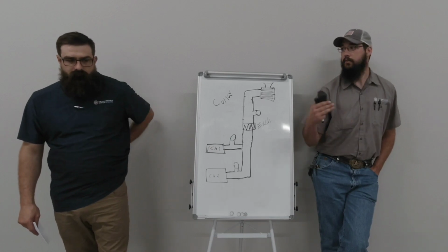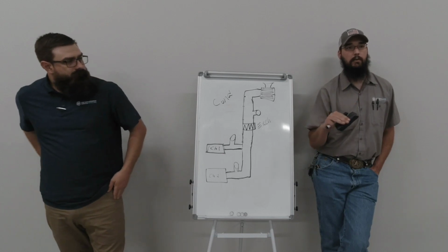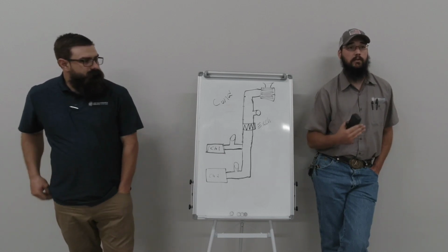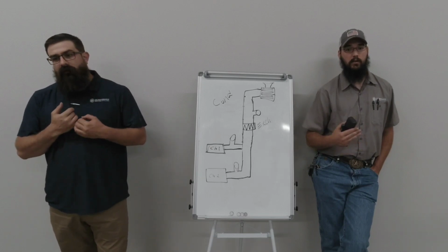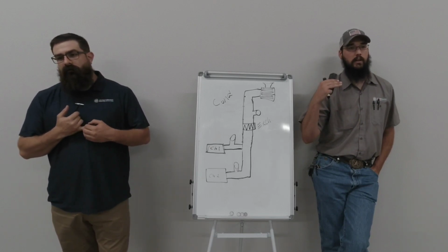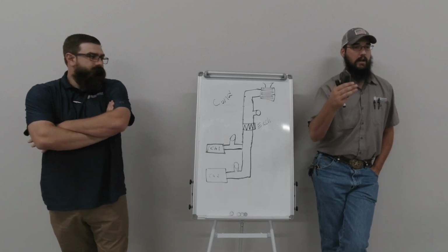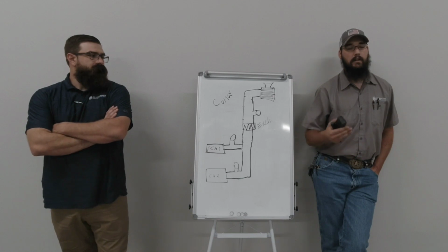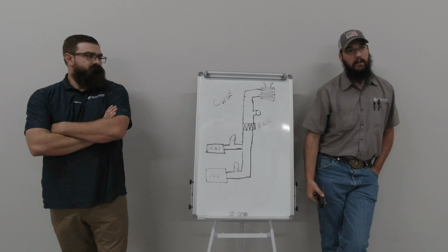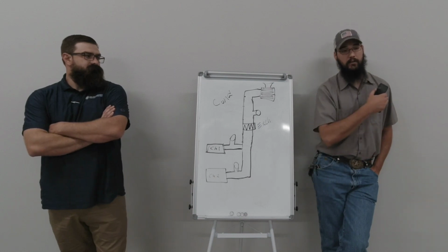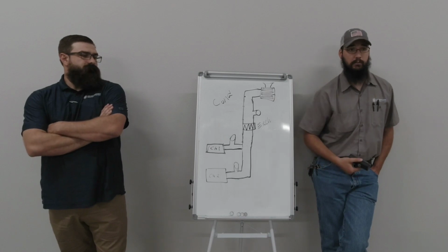The way I would troubleshoot, there's no set standard like we have on a lot of stuff when it comes to that pressure drop. It is extremely equipment specific. And so the way I would troubleshoot that is, say I've got a water source heat pump. I've got 85-degree water coming in, and 100-degree water coming out, and I've got 60 pounds of pressure coming in, and say 15 pounds of pressure coming out.